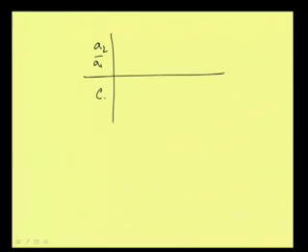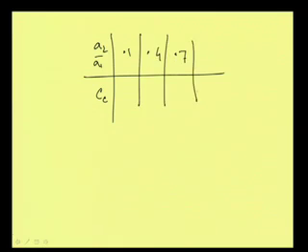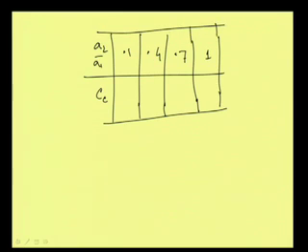Then, as I said, we have this sort of ratio, A2 by A1, and then we can have the value of Cc, for 0.1, 0.4, 0.7, 1. 1 means this pipe is not having any contraction. So we get this sort of table, and it gives Cc equal to 0.624 when A2 by A1 is 0.1.